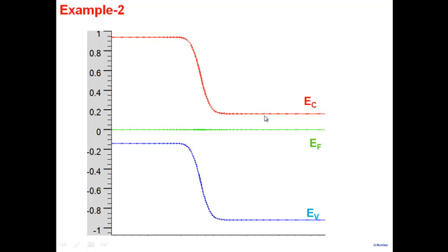I have a high concentration of electrons here and fewer here. So electrons will try to diffuse from left to right here. So you can see all of those things from here, right? There'll be a diffusion current here, and there'll be a drift current here. Electron drift and diffusion currents all cancel each other. The same thing will happen with holes also.